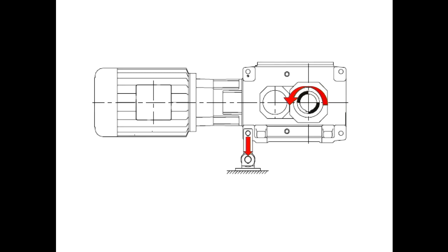Remember, if I've got a torque, but I actually do it with two forces, I've got one force up and one force down. If I've got a real wheel brace on the car and I'm trying to get this nut off, and I jump on the wheel brace to get that nut starting to undo, the wheel brace wants to go down here, but it also puts a force here on the nut, and it has to be reacted, right? Are we happy with that?